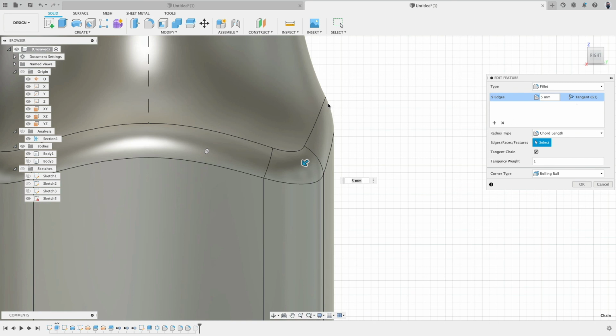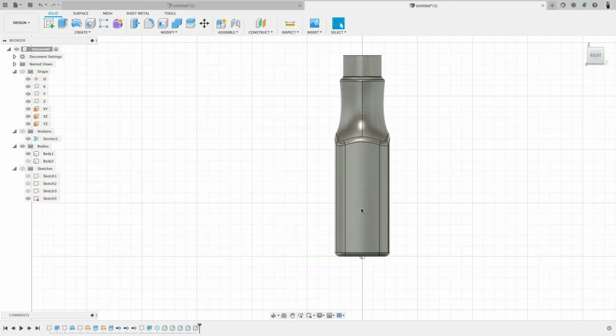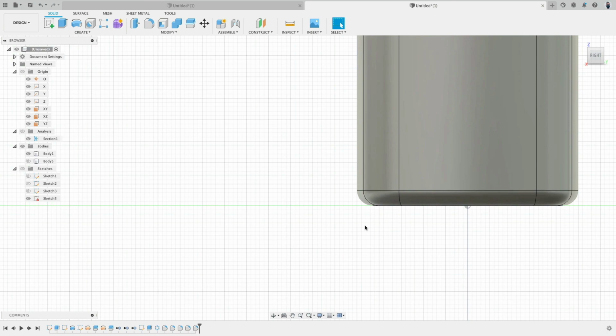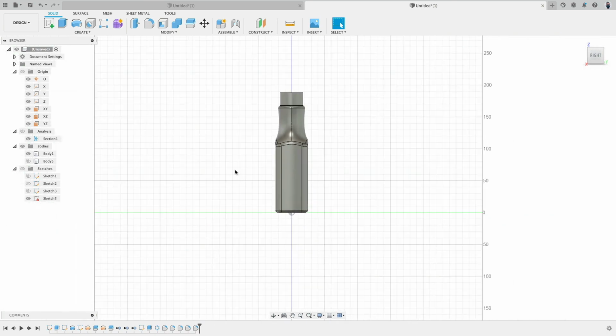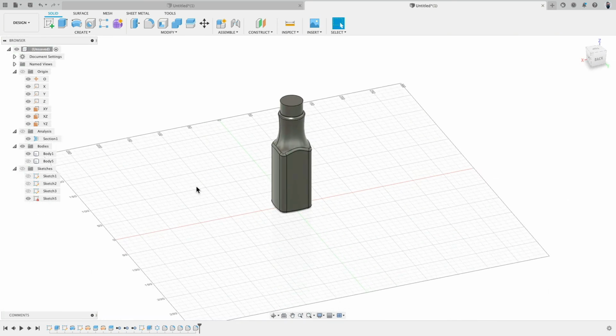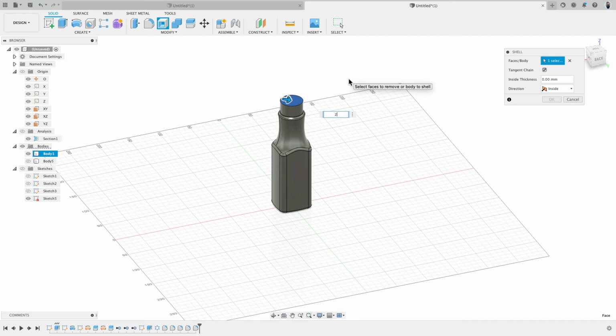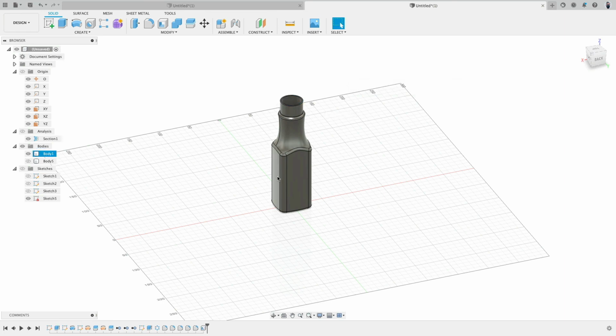between tangent. Oh, you see like it comes down and whoop, changes instantly. It's terrible. There it comes down, continues, changes, and then stabilizes. It will feel actually noticeably better. Down here, this at the bottom, we can keep it G1. Again, G2 features are more time consuming to calculate, so only use them when needed. Sweet. So 2mm for the shelling. You also notice that it took a little bit longer to shell. If we have all those G1 fillets, it will be faster.